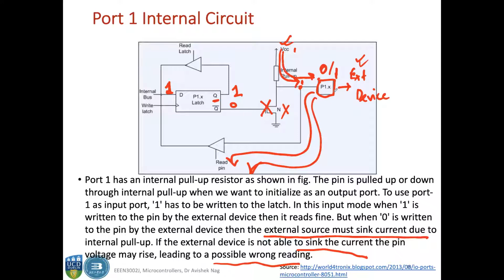So this has to be kept in mind. Otherwise, the general arrangement is that to read from this pin, you have to put a 1 here, and then only you can read from this port 1.